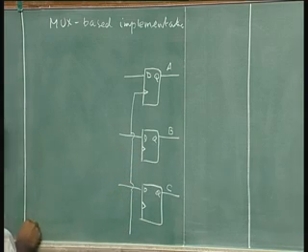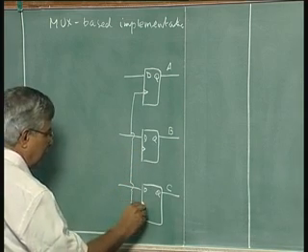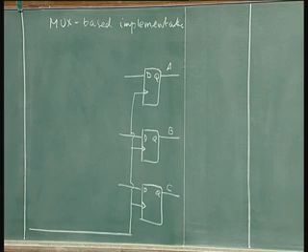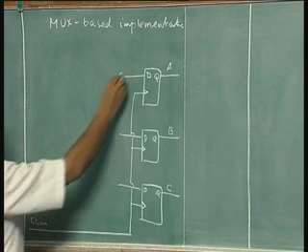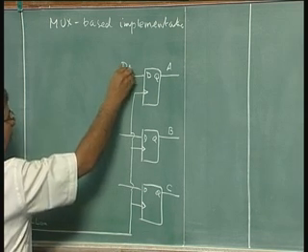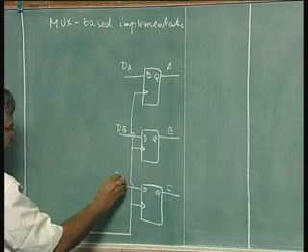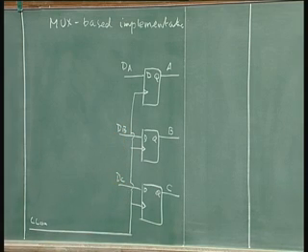So, my aim is to reduce the combination logic ICs used, the number of ICs used in combination logic. Instead of having a variety of gates of different types, can I use multiplexers and get this? That is my question. So, DA which is the input to the A flip flop, DB which is input to the B flip flop, DC will now come from multiplexers instead of gates.